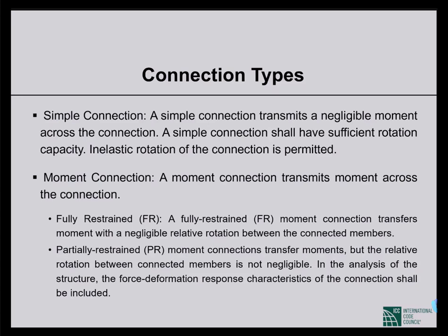In this case, if we plot the moment curvature relation, that gives a nonlinearity into the system. So if we use partially restrained connection, and if we want to take that into account in our analysis, in that case, we have to go for nonlinear analysis.